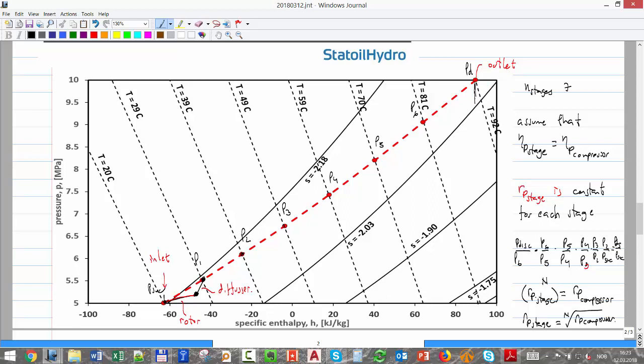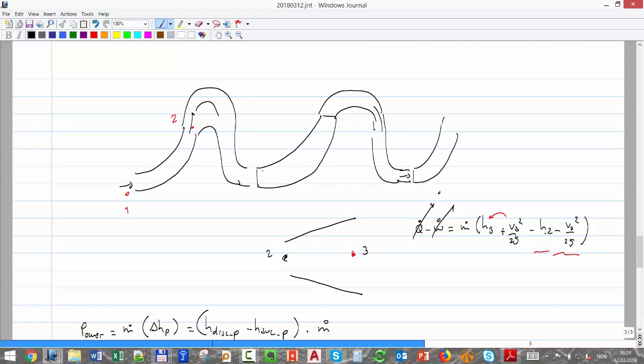But that's only on the side of the fluid, if I was so efficient that all the energy is received by the fluid and nothing else. Actually, I will need much more energy, because that process has an efficiency. I have all kinds of losses: volumetric losses inside the machine, friction losses with the blades, recirculation losses with the passages. The flow doesn't go exactly straight, I have some eddies and turbulence. So I have energy losses all along the machine.